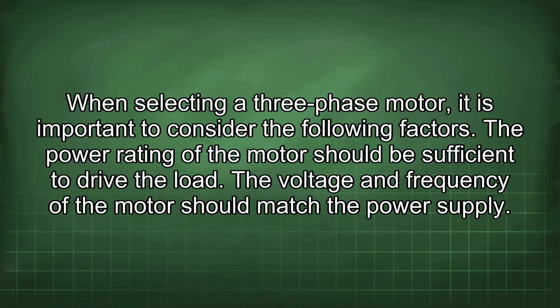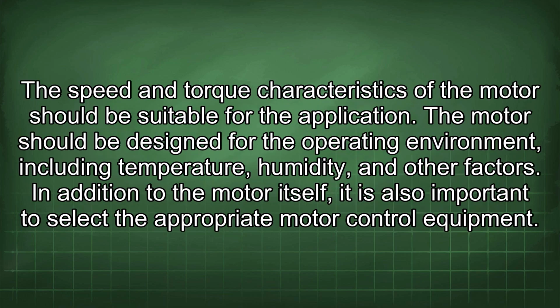When selecting a three-phase motor, it is important to consider the following factors. The power rating of the motor should be sufficient to drive the load. The voltage and frequency of the motor should match the power supply. The speed and torque characteristics of the motor should be suitable for the application. The motor should be designed for the operating environment, including temperature, humidity, and other factors.